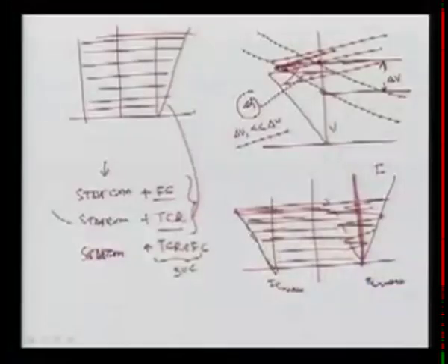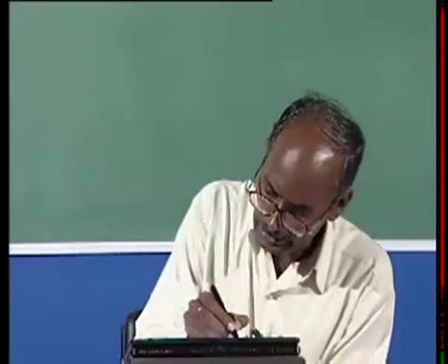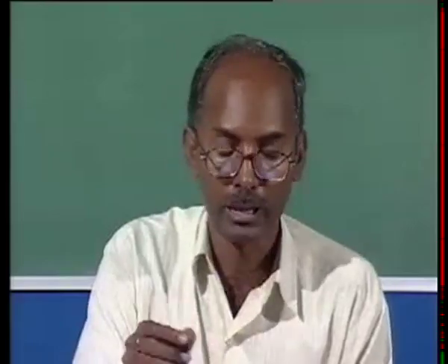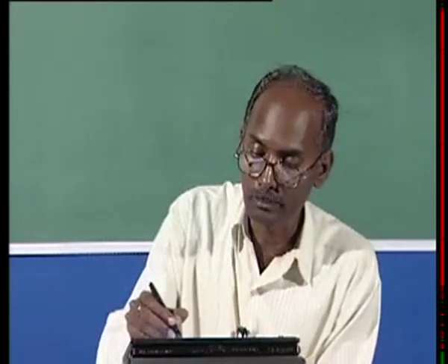Here again I want to show you that reactive power supply is one objective: whenever they are connected, they normally feed reactive power, or they can absorb it whenever required. The STATCOM or SVC will inject reactive power into the system when the voltage is less.